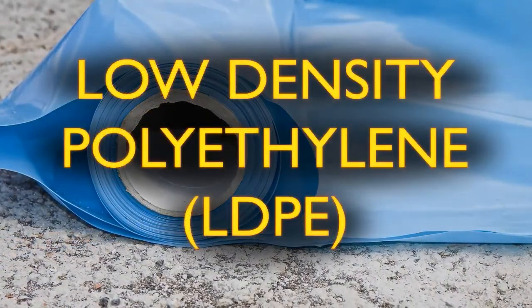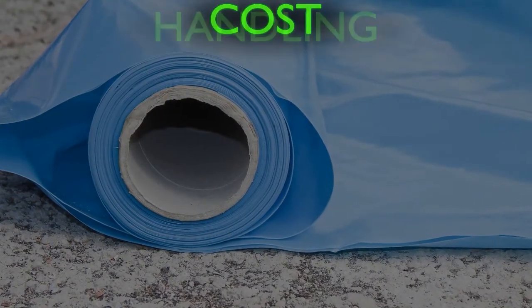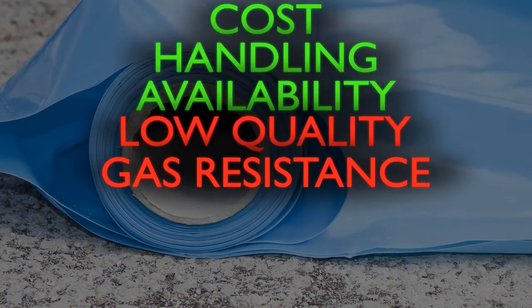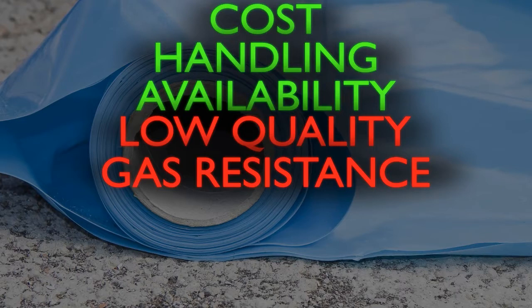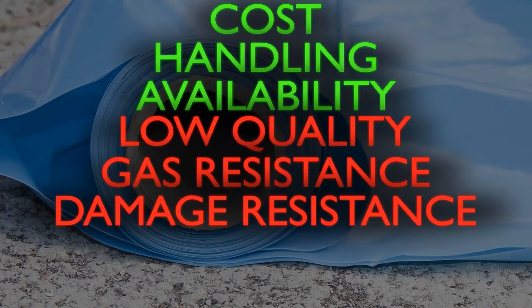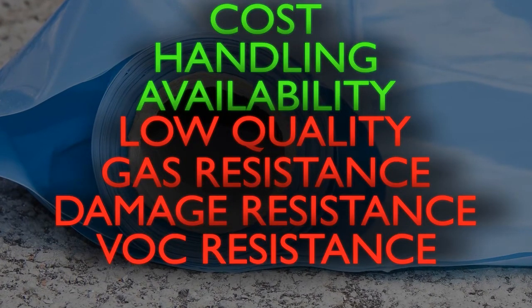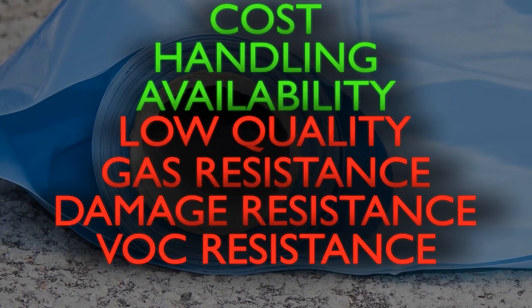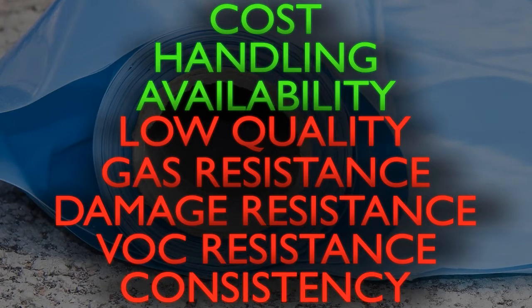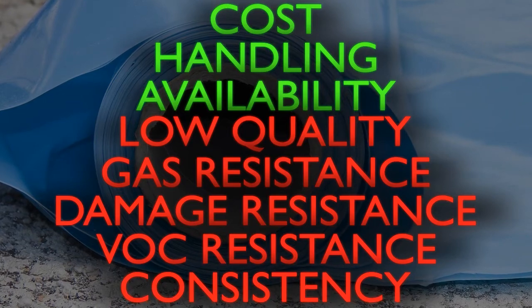Low density polyethylene, LDPE. LDPE membranes are standard DPM materials which are cheap, easy to handle and readily available, but can be low quality and are generally not suited for gas resistant applications due to their high permeability and limited resistance to damage and UV. LDPE membranes' resistance to VOC transfer is particularly poor, and these membranes can degrade rapidly if directly exposed to chemical contamination. Low-grade LDPE can also have problems with manufacturing tolerances, resulting in a material that, while water-resistant if undamaged, will not deliver consistent and robust performance in gas protection applications.